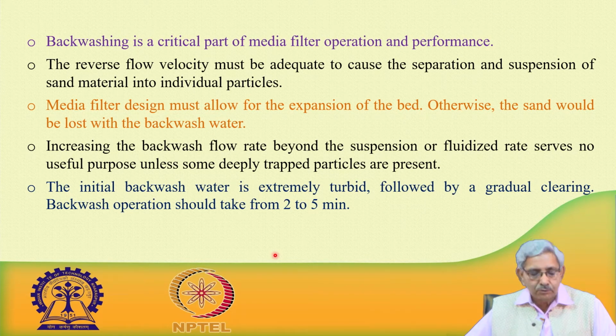This is the important part, and we need to see that the initial backwash water is extremely turbid. So, we need to check the quality of the water coming out of the filter system. Time to time, for 2 to 5 minutes, it should be brought into the backwashing mode after operation, and the quality of water should be checked.